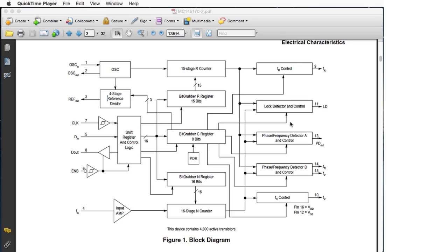There's also a fixed reference divider, which comes off the reference oscillator, which is usually a 10.24 megahertz crystal. That's either directly on the pins of the PLL with it using an internal oscillator, or it's fed in from an external oscillator on the board, like on a Cobra 29 for example.